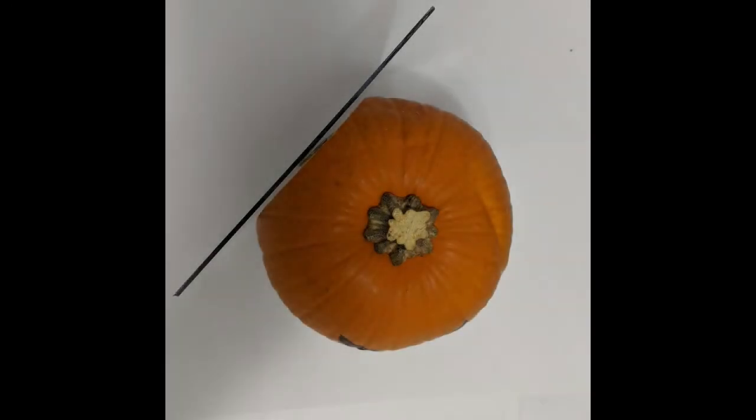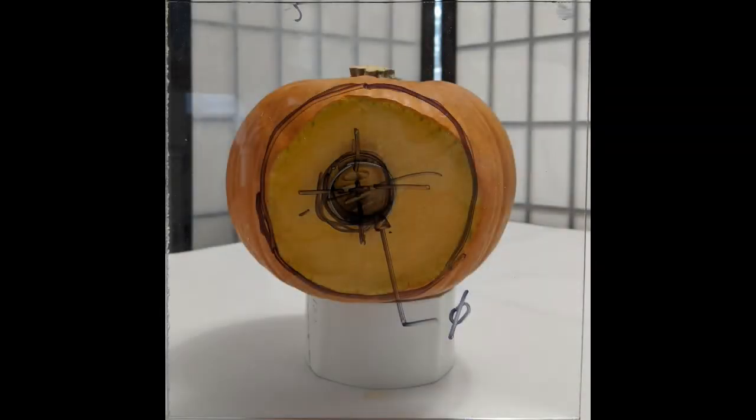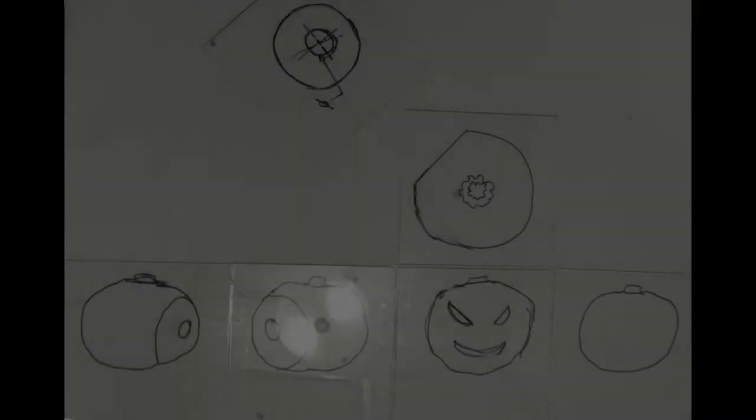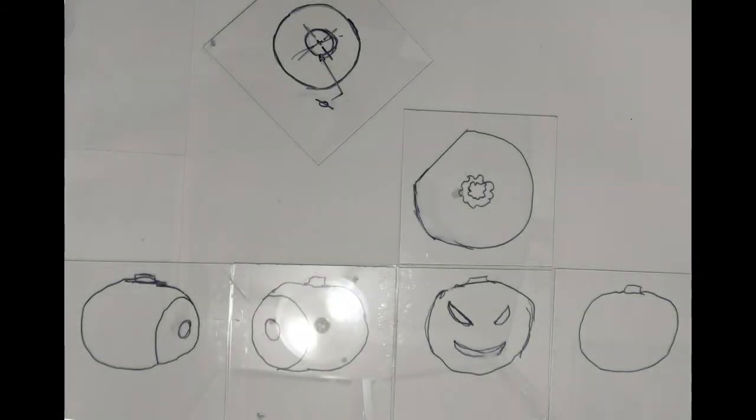If we want to show the true shape and the true size of the flat, we need to first make a plane that's in the same plane as the oblique feature. We then can look directly and project view-point lines from the feature onto that oblique plane. Then we fold the oblique plane down to produce our auxiliary view where we can dimension things in real size. In this example, it's a partial auxiliary view because it is only displaying the surface of the oblique plane.